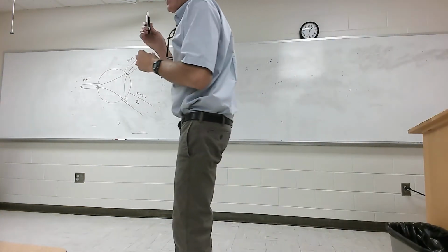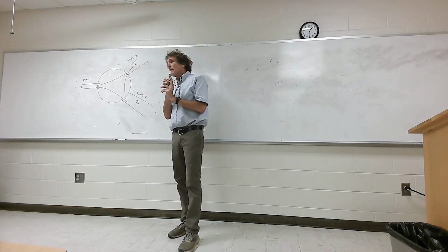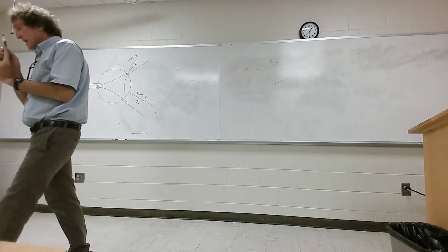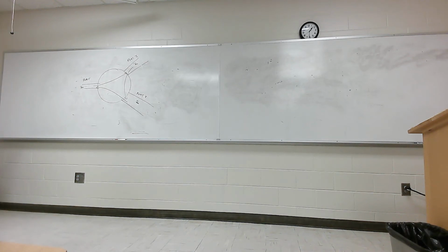They use magnetic materials. Do y'all remember that if you had a B field and a charge flying through it, it would bend one way if it's positive, the other way if it's negative? Well, they'll have magnetic materials so that as this electromagnetic wave is propagating, small amounts of it will bend one way. Everything coming in will bend one way, and everything going to the port will bend into the port.